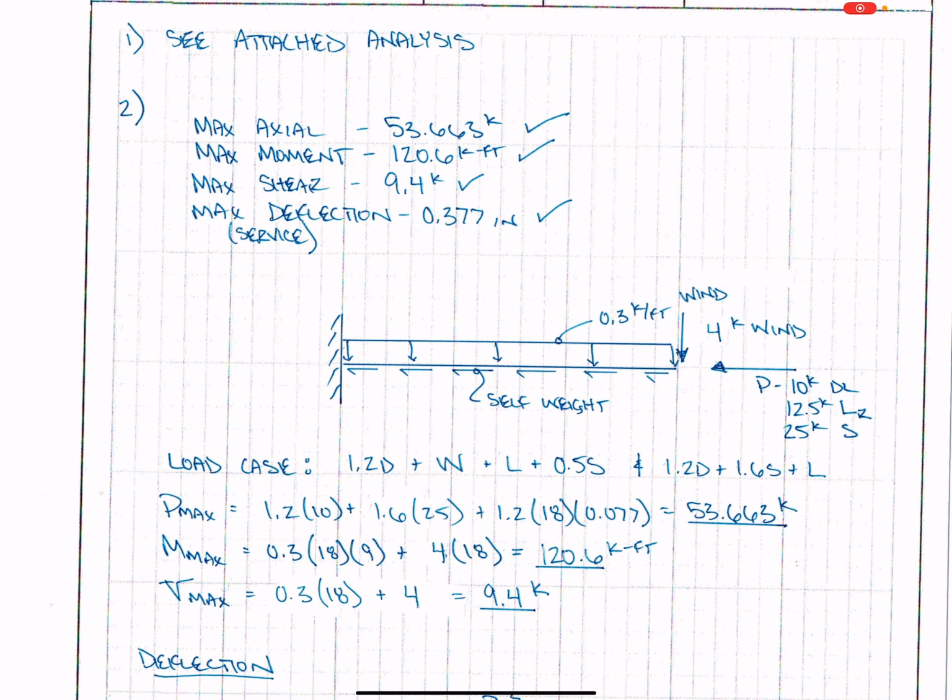Right? We did talk about the modal analysis method. I mean, we ignore some self-weight stuff, and there are areas where you would. If you explained that, okay, I ignored it because, say, it was maybe 1% of the overall applied loads, fine. If you just said I ignored it because it's a more accurate model, that is not right, right? The most accurate model would be incorporating the self-weight of a member. So you just want to make sure that if it's there, you account for it.